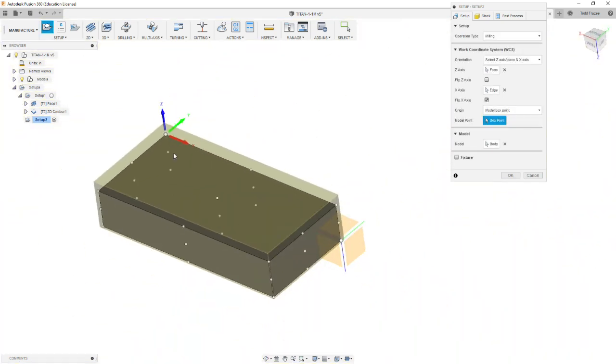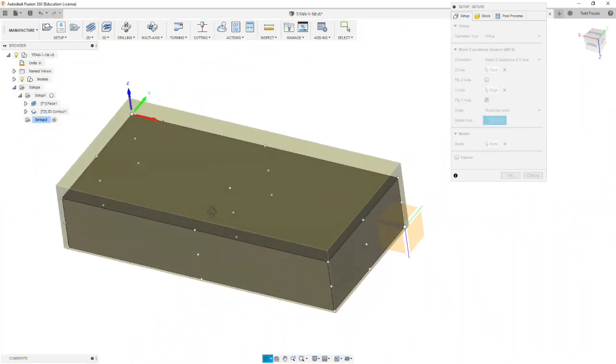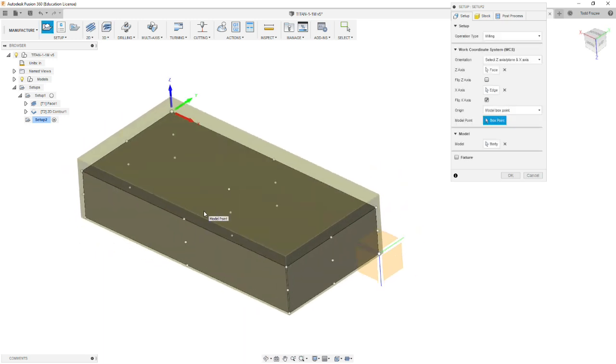You never want to base an operation off stock for anything but the very first operation. The stock is raw cut. It's going to be off by how much you offset when you first set up. Every following operation should be based off a machined face that you can indicate to. Okay, and we'll work with you in the shop on proceeding with that.